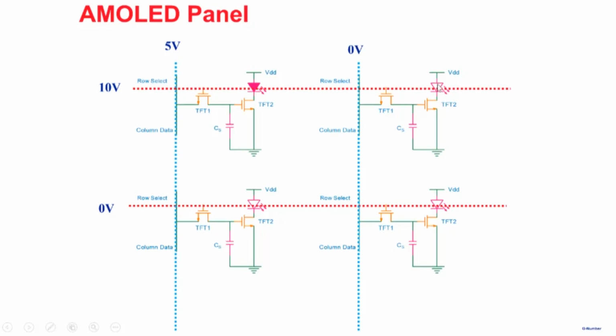In this case, we don't want this LED to be on. So what we do is we pass 0. When we pass 0 here, this switch turns on. And even if this LED was on earlier, and there was some charge on the capacitor, it will immediately discharge to 0 through this switch here. The capacitor will discharge and this LED will be 0.